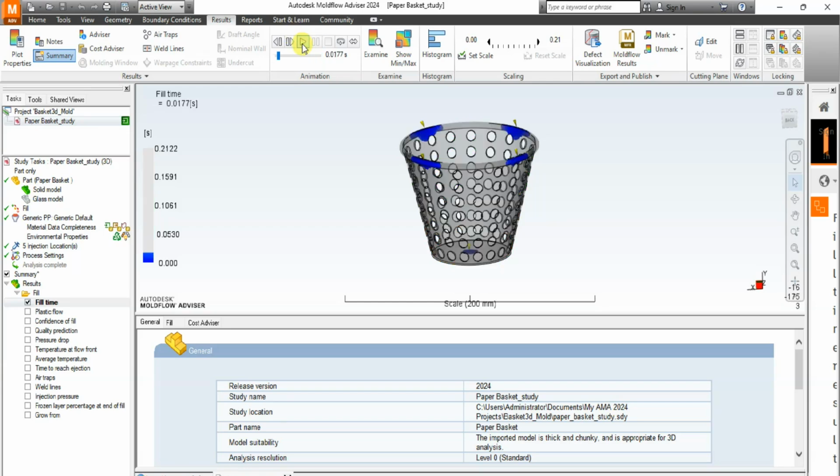In this particular diagram, you can see that each flow part ends with the red contours. The contours are evenly spaced and indicate the speed at which the polymer is flowing. It's very, very important you take note of that. Widely spaced contours indicate rapid flow. Narrow contours indicate the part is filling.